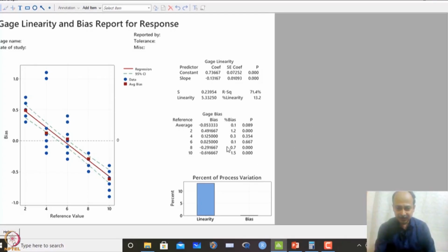Okay. But when we are doing this study, one thing we get is the linearity percentage that Minitab also reports, and there can be different criteria for different industries. Somebody can take 10%, somebody can say anything less than 30 is okay, but there needs to be some corrections over here. So, percentage linearity is a concern. Whenever it is more than 30%, it is a concern, that means it is highly significant. In that case we have to take some measure, because the bias is changing drastically in the operating range, and we will get the information on where it is changing over here. Okay.